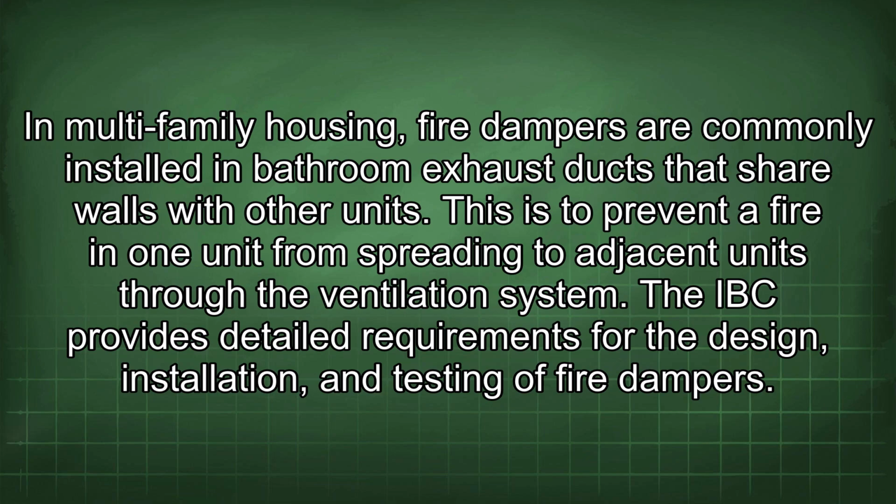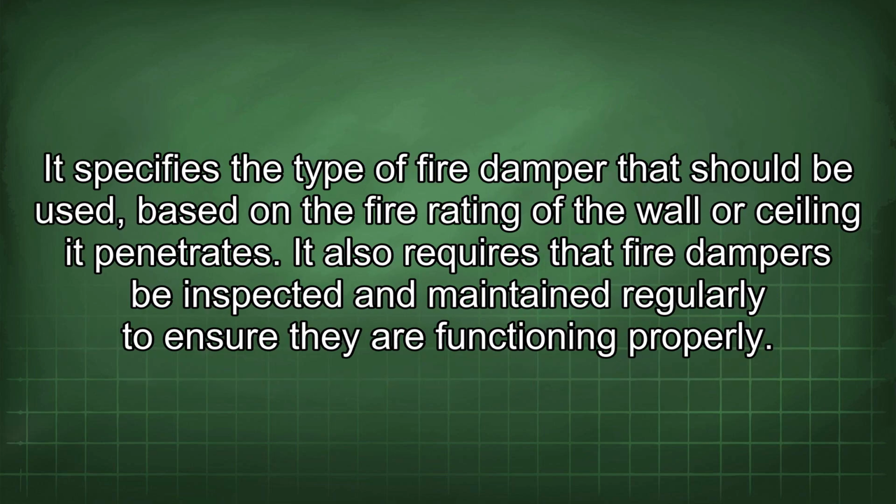The IBC provides detailed requirements for the design, installation, and testing of fire dampers. It specifies the type of fire damper that should be used, based on the fire rating of the wall or ceiling it penetrates. It also requires that fire dampers be inspected and maintained regularly to ensure they are functioning properly.